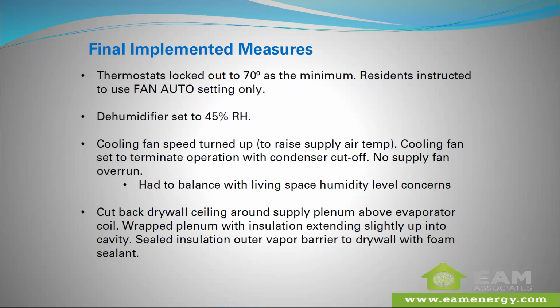I'll note on those, those wall-mounted or kind of R2D2 style standalone dehumidifiers, it's something in a home that's having problems, and maybe in a small apartment they can have more value, but the problem with them is that they inject air and exhaust air in the same space. They're not creating any kind of a flow gradient.